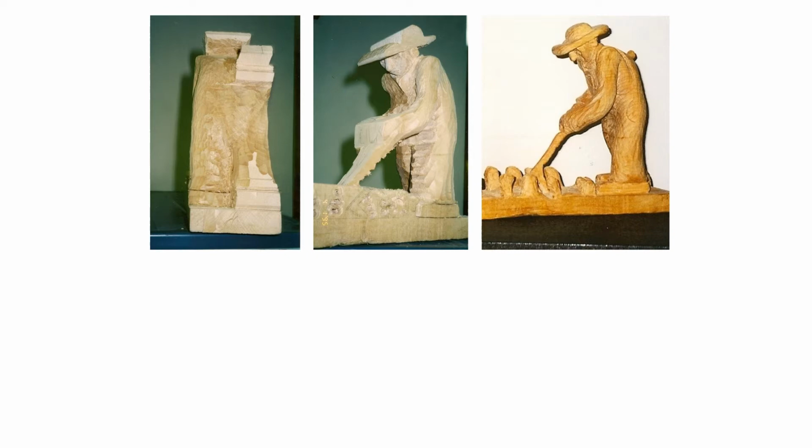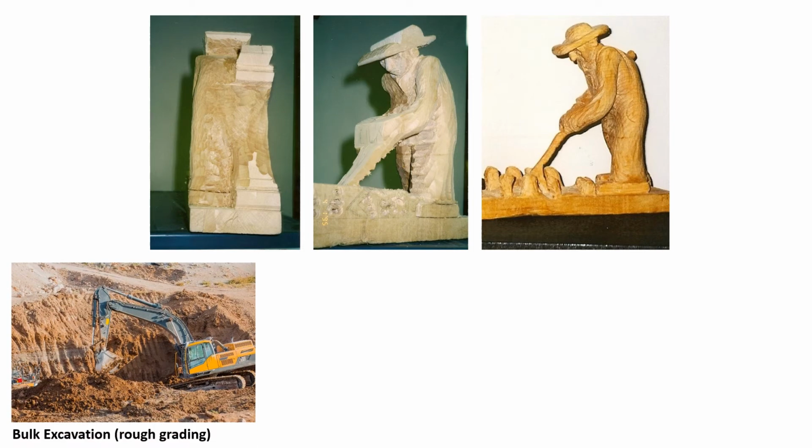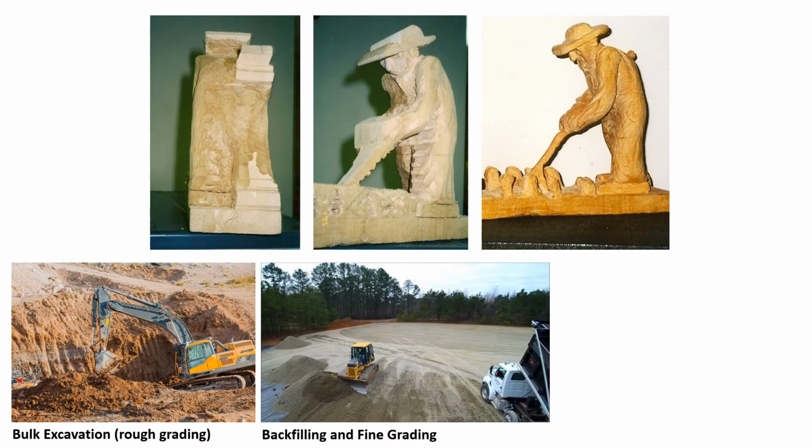There are many steps for site preparations, but I'll only explain 3 key ones. So first, bulk excavation, aka rough grading. This is where the majority of earth moving and shaping take place. And you also need to excavate for the footings and foundations if you have any buildings or other structures, right? Once that is finished, once the footings and foundations are built, you need to backfill the excavations for structures.